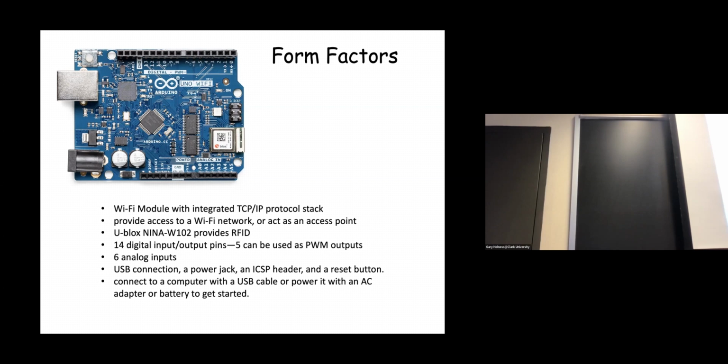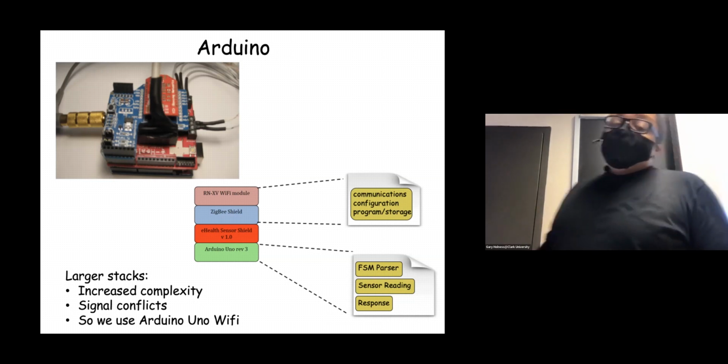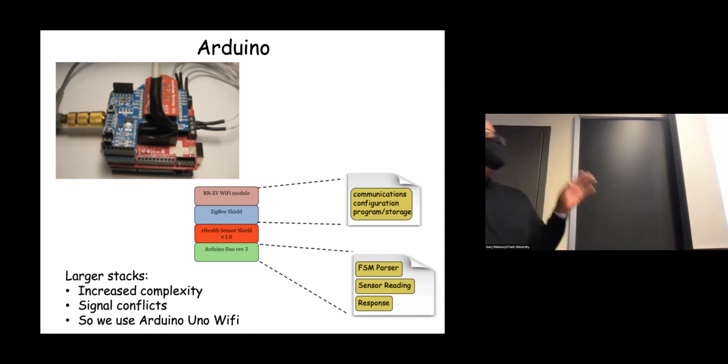Okay. We also talked about this idea of these daughter boards, so-called shields, that you can plug in to the base Arduino, the credit card sized Arduino, like the Uno 3 and variants like the Wi-Fi revision 2. And you can use these shields to extend its capabilities. Things like the GSM shield are immensely useful because it allows you to engage in telemetry using the wide area over the cell phone access network.